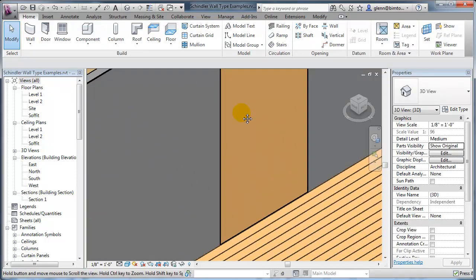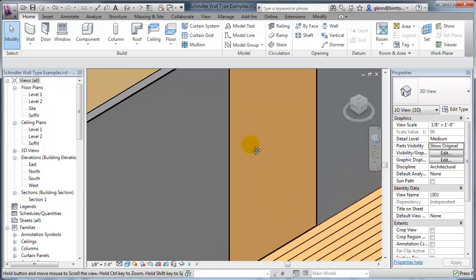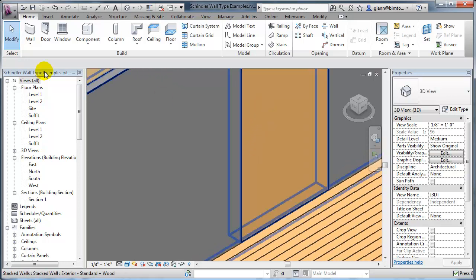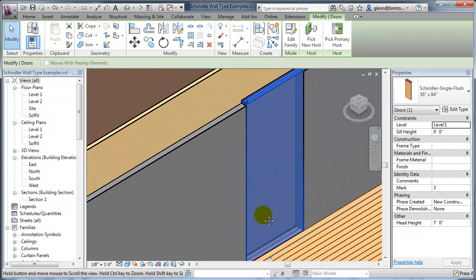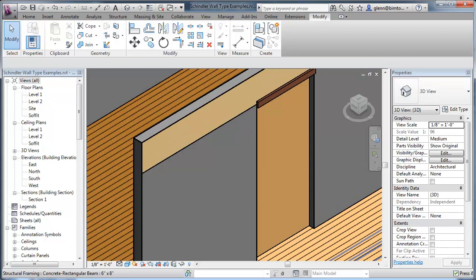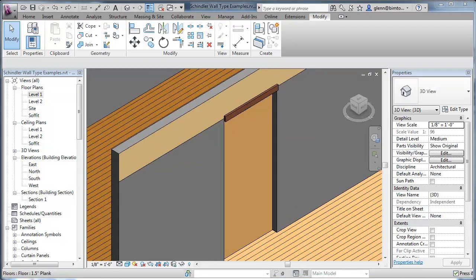That's looking a little bit tall in terms of what's going on over there. Why is that looking tall? Let's think about this. I made it 91 inches. I think I want it to be 81 inches. Okay, we've got that door in there. The head height, or the head trim, doesn't look quite right yet. Let's go ahead and take a look at that.